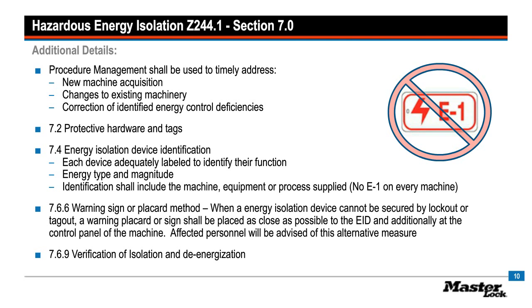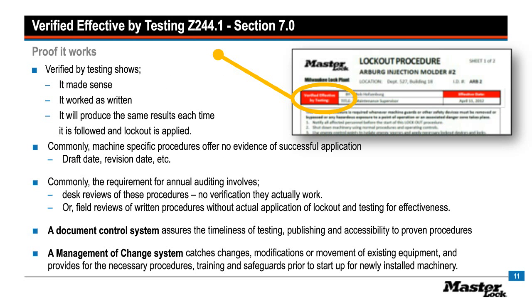Verified effective by testing. This was a very important discussion, as many times what we see in standards are an author of a written procedure, an approver of a written procedure, a reviewer of a written procedure, and a reviser of a written procedure. That documentation all is valuable, but did the procedure ever go out to the workplace and get applied in a manner that demonstrates the procedure speaks to the right order of isolation, and does it speak in a language or a level of language that the intended user can work with?